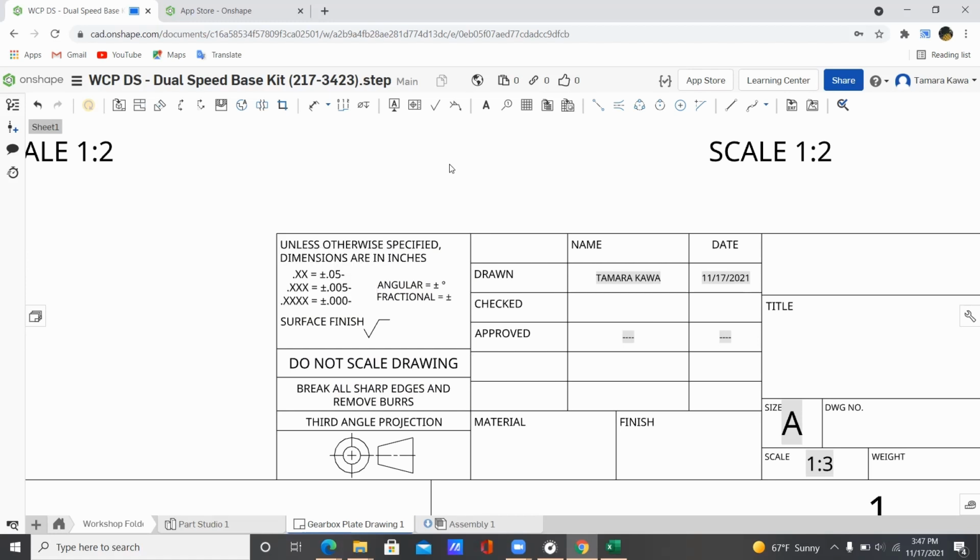As a note, in some cases, again, I don't think this is applicable to the team, but there are cases where your tolerance isn't going to be plus minus the same number. There will be cases where you can go 0.05 over, but you cannot go under, or cases where you can actually go a little more over than you can go under. So I just thought I'd highlight that because it's an interesting feature.